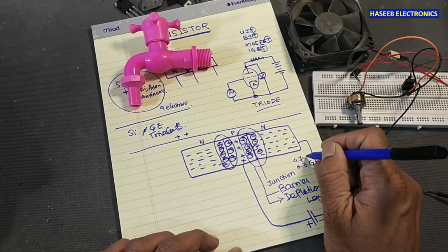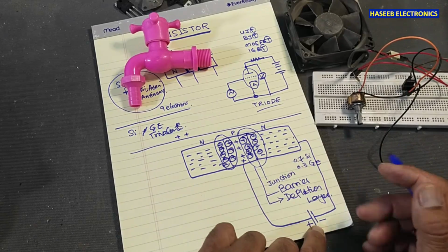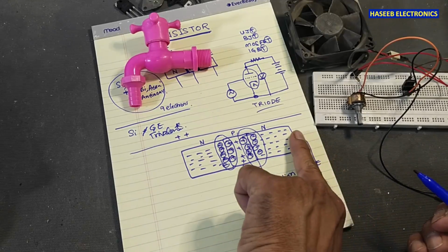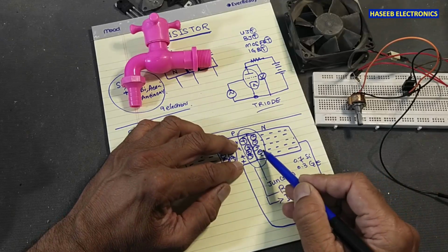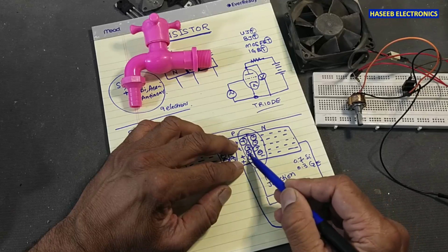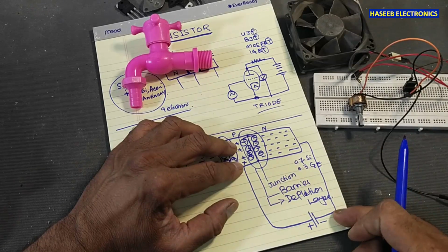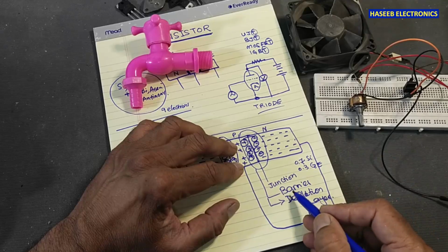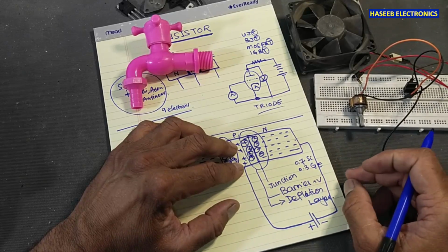These voltage will increase, so the electrons will be pushed into this area, and after that here we have positive charge. When this potential difference is above this voltage, it is called barrier voltage, depletion layer voltage, or junction voltage.